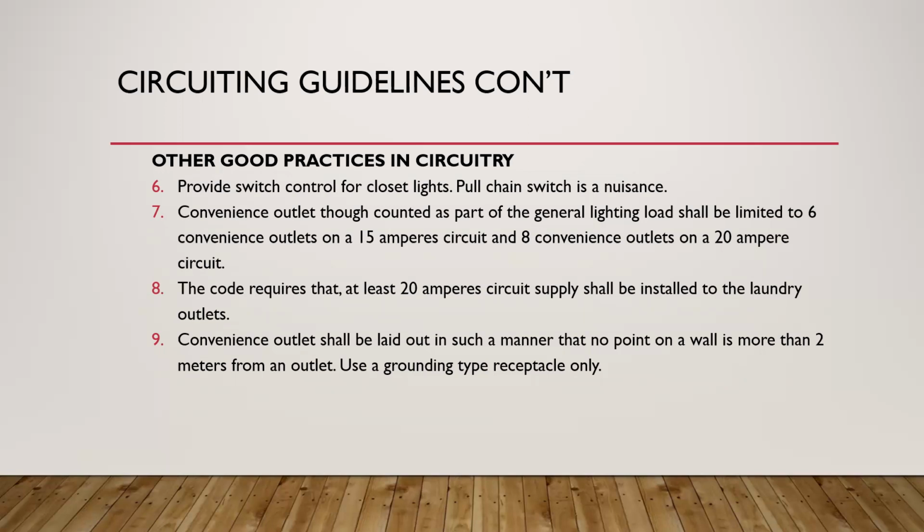Number 7, convenience outlet, though counted as part of the general lighting load, shall be limited to 6 convenience outlets. Sa convenience ha, so in your analysis, at least kung susunod kayo dito sa ating good practices in circuitry, maximum per circuitry, if you consider the convenience outlet, 6 lang.